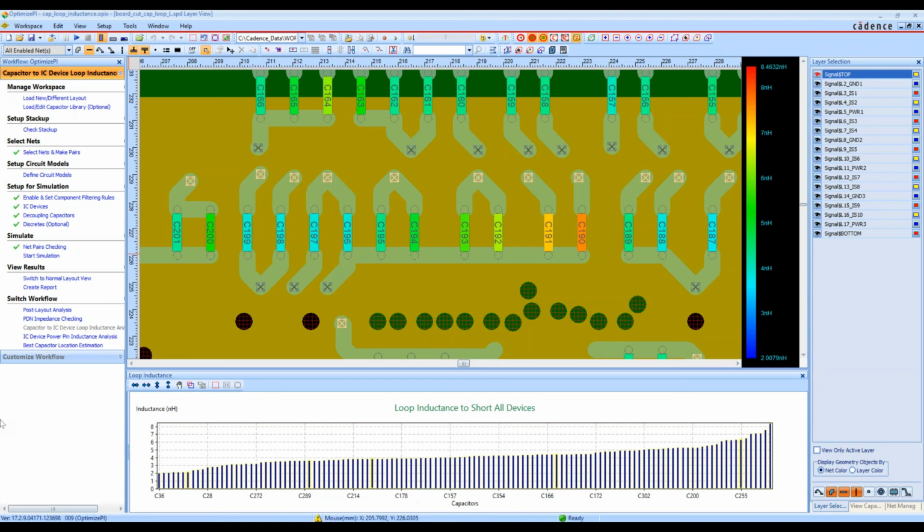Those are typically out of the realm of our customer base. Our customers are normally doing printed circuit boards, not ICs. So you're relying on your manufacturer to have done that correctly for you at the very high frequencies. Theoretically, there's not really a limit of how high we can go in frequency, but practically it doesn't make much sense to go too much higher.